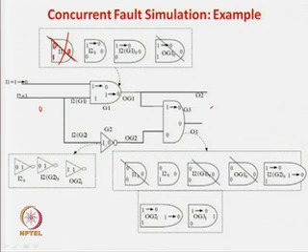Now, let us take the third gate. The third gate was I2 G1 stuck at 0. So, this line is stuck at 0 over here. So, now the signal you are applying here is a 1, this is a 0 over here. So, in this case this is a 0. So, we know that this is stuck at 0 over here, this signal is 0, this is only a change over here, and this thing is retained and this thing is retained.